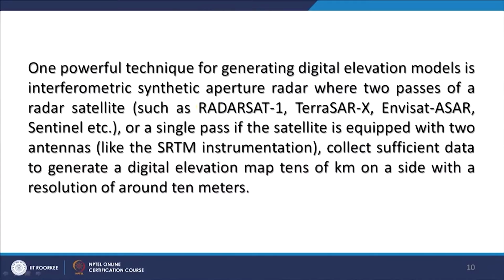And this SAR interferometry technique for generation of digital elevation models basically started with the satellite called RADARSAT, because that allowed us to create a pair, not a stereo pair, but a radar pair, and later on, using this interferometry technique, digital elevation models were prepared.